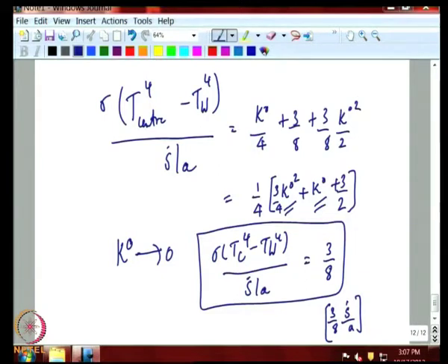So, from these exercises we have understood the role of internal heating, as in this case, or the role of wall emissivity, which you saw earlier in this lecture. So, we have done two problems in this simplest gray gas case, one involving radiative equilibrium and the other involving heat release in enclosure, which has to be removed from the gas by radiative heat transfer to the wall.